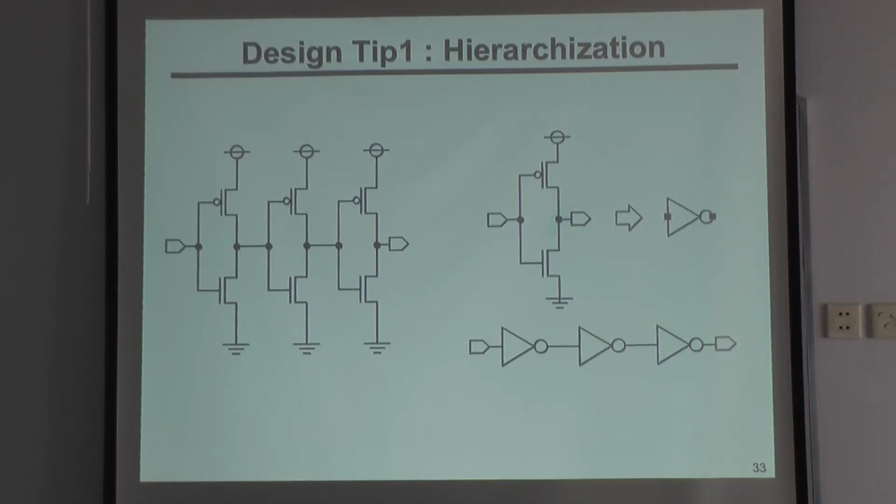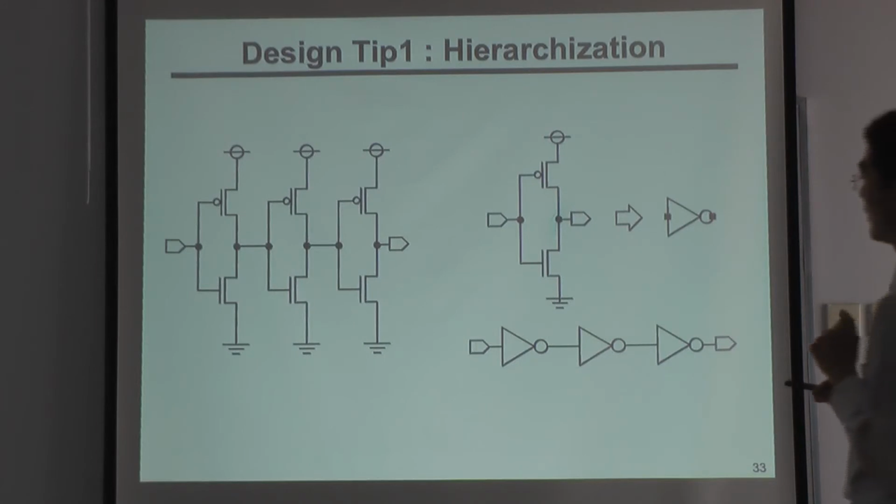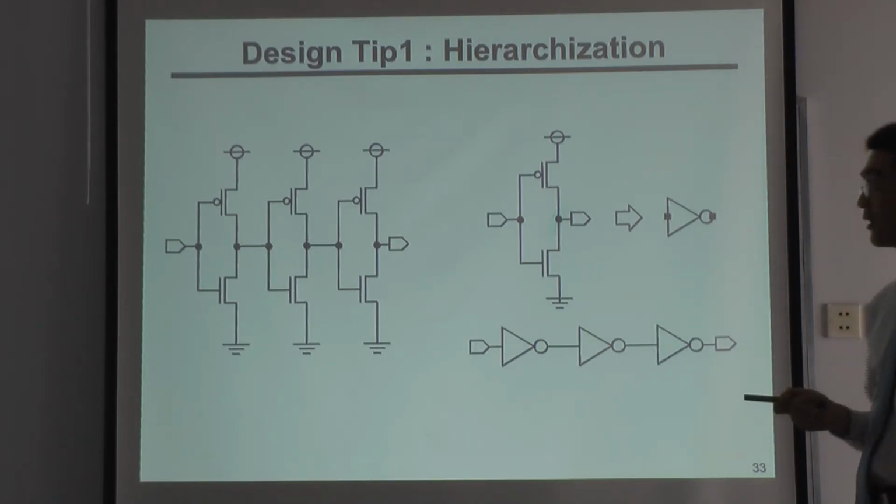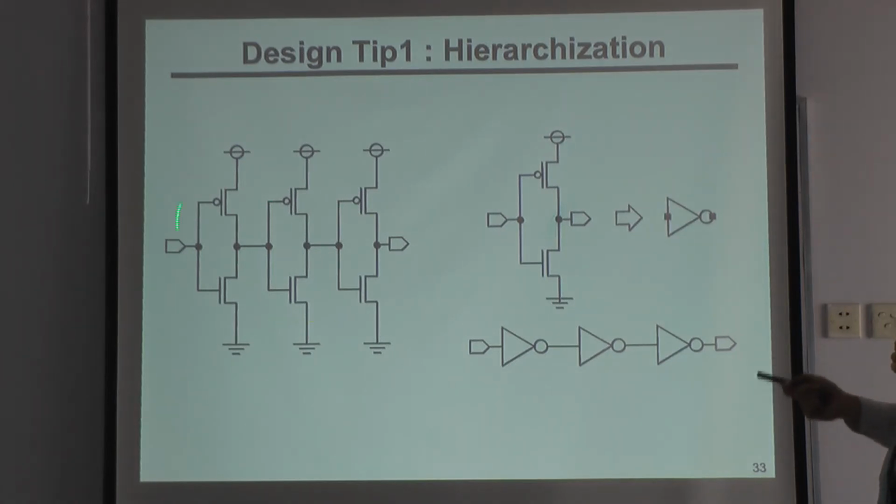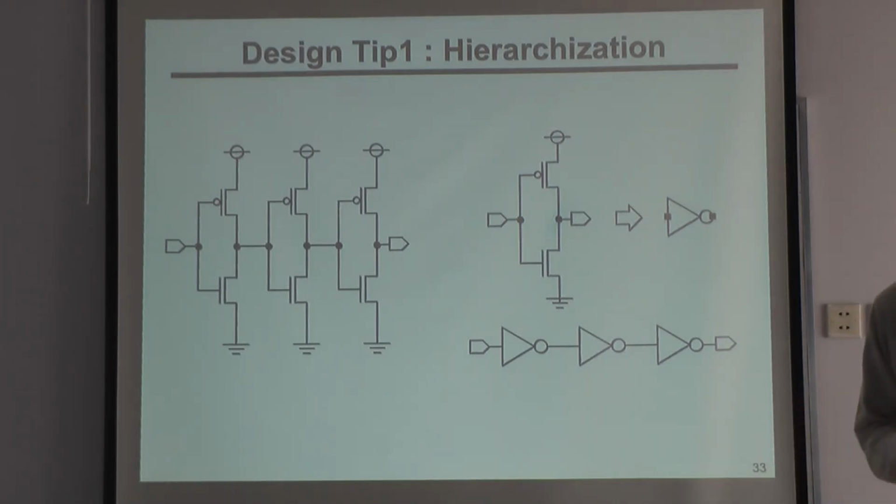So when we design a circuit in Cadence, for example, when we design an inverter chain like this, you shouldn't design it like this. First you design an inverter and simulate it, and then you put a symbol, making a hierarchical design, and we strongly recommend you to use hierarchical design.